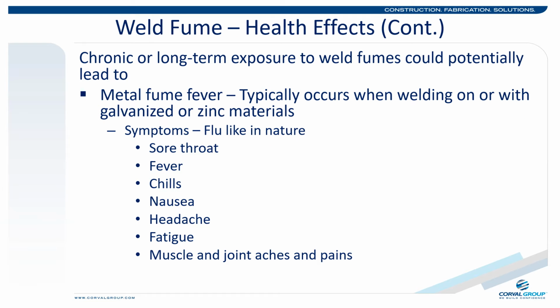When welding on galvanized or zinc materials, a welder can experience what has become known as metal fume fever within just a few hours of welding activity. Metal fume fever, MFF, has nonspecific symptoms, but is generally flu-like. Symptoms may include sore throat, fever, chills, nausea, headache, fatigue, muscle ache, and joint pain. A sweet metallic taste in the mouth that distorts the sense of taste is commonly reported. If you've been welding on zinc or galvanized materials and experienced the above, notify your supervisor immediately.